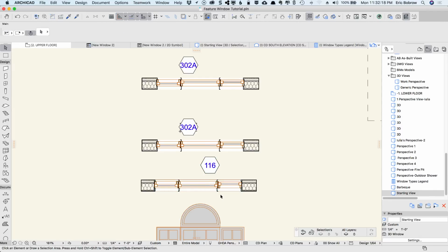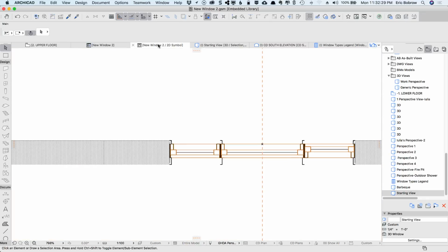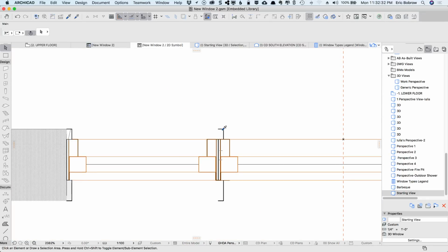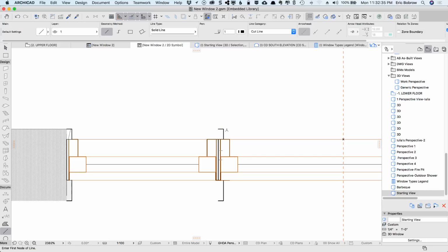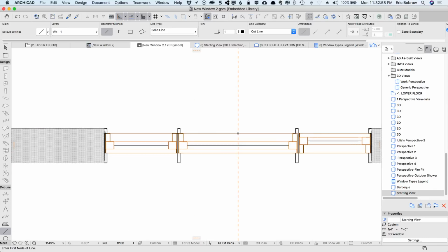Looks exactly the same as before. Now I may want to actually clean this up a little further. For example, because of the stacking windows, we don't have a full frame here. So I'll just do a quick little test where I pick up the settings of this line and draw this down here, draw that down here, and perhaps do this here. Now, I'm not sure that this is exactly the way the symbol should be. Maybe the framing should be different, but it certainly looks a little bit more complete now.